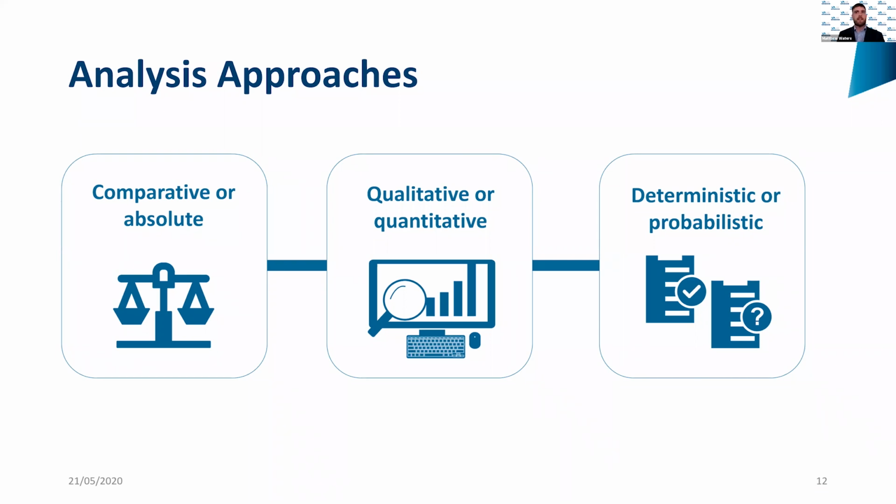Probabilistic is a risk-based methodology, and it looks at assigning reliabilities to the performance of measures and then assigning frequencies of occurrence of different events occurring. So it looks at a number of event scenarios and then an estimate of the likelihood and consequences of the scenarios, and it looks at evaluating the risk. A common example of this is event tree type analysis, which is used in fire engineering for doing things like the design fires and things like probability of exceedance.